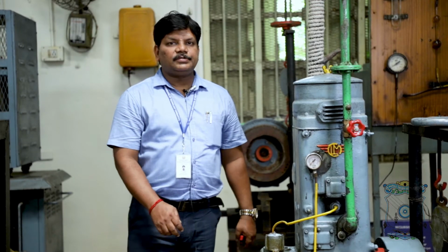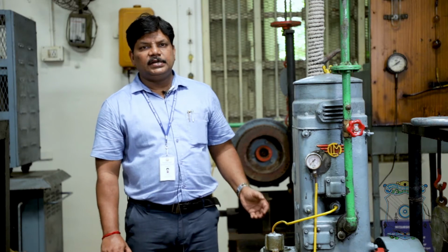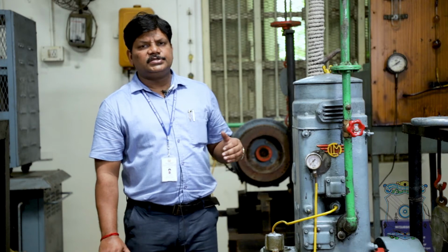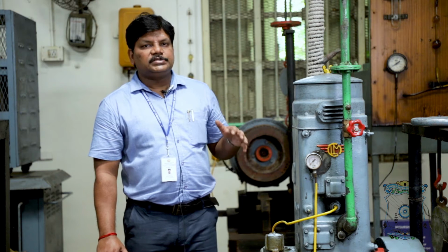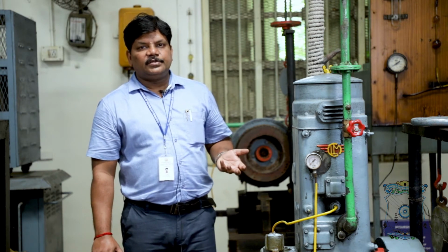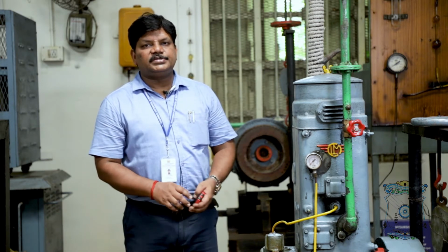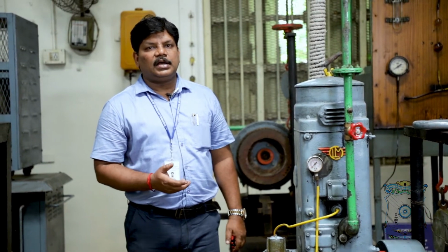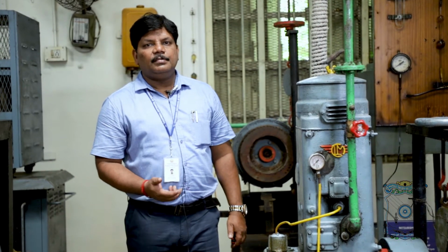Initially, we started the engine and ensured that the speed is 1500 rpm. If a load is given to this engine, we have to maintain the load as constant. For that, to find the maximum load, we went for the effective radius. We measured the radius of the brake drum and also the radius of the rope. We find the value of capital R and small r, and if you add them, you will get the effective radius. From that we found the maximum load.